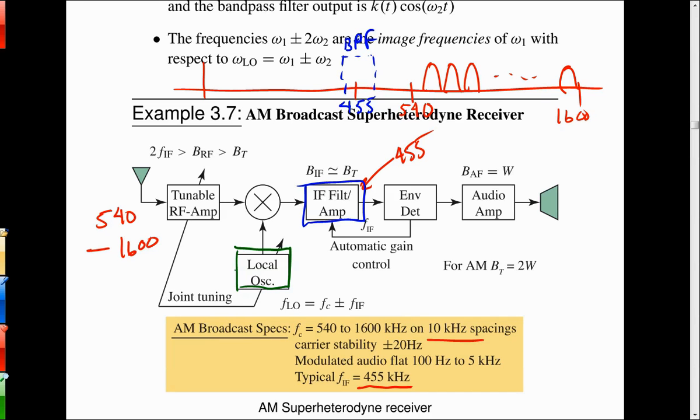We get our options actually with a frequency translator, and I didn't really dwell on that before, but the output we can choose is either the sum or the difference. It doesn't have to be the difference. It just is one of the two that we would like to have. So in this case, though, it is the difference that we're looking for. The difference is at 455. And if you look at the simple math involved, I can't do anything with 540 by adding a frequency onto 540 to get to a lower frequency. Do you agree with that? So I do have to use a difference.